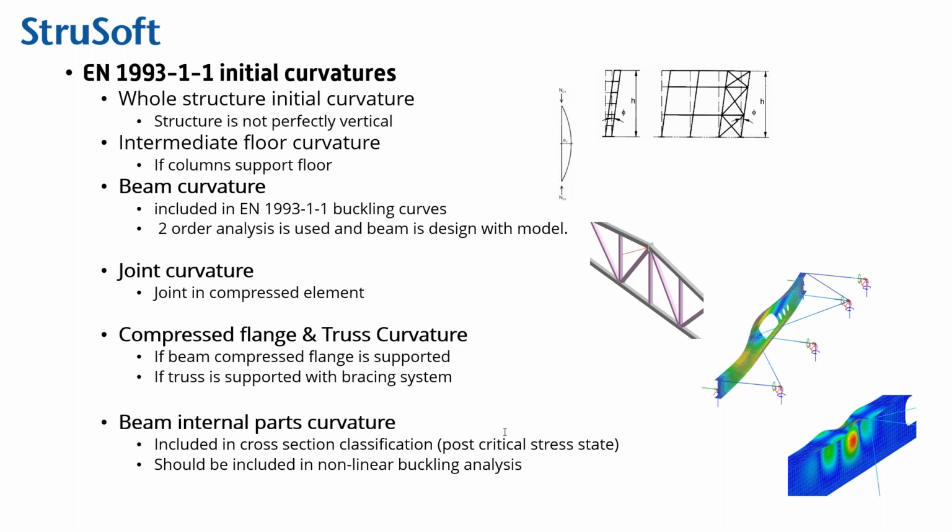So in your case, if it's like 150 millimeters of gravel, it would be a really high number, 250,000 kilonewtons per cubic meter is a ballpark estimate. But if you just Google bedding modulus of subgrade reaction, you get some initial values. And in our software, it's also possible to actually calculate this.